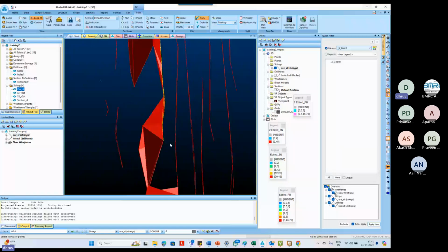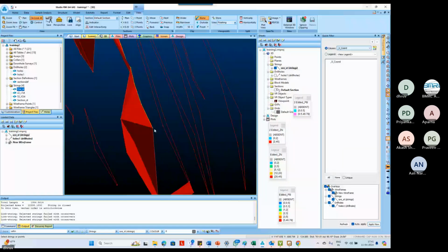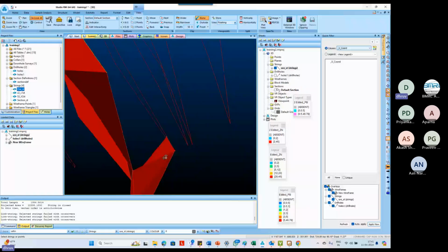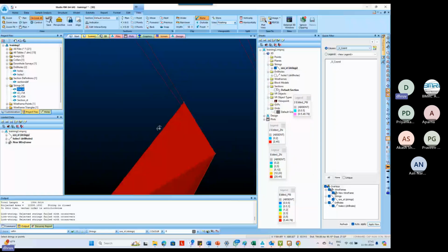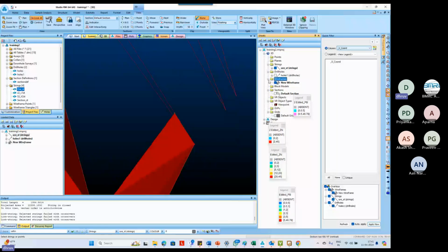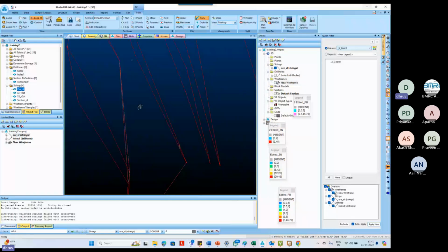So what we want is for this string to come here. There are two strings, so let us switch off the wireframe to see it more properly. Switch off the wireframe. Okay. Now we will do a tagging. TGS. This. This. This. Escape.